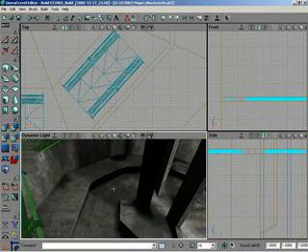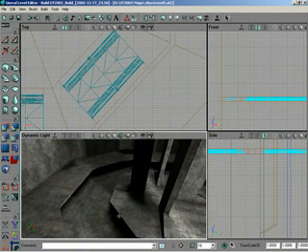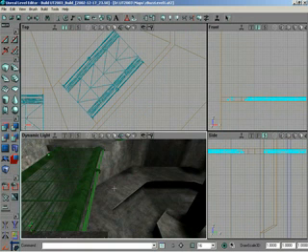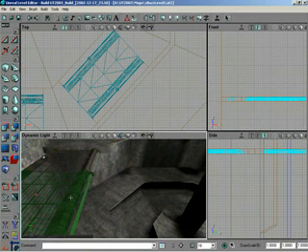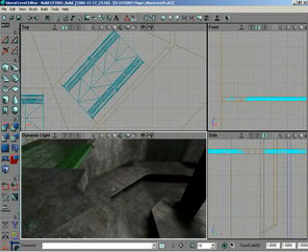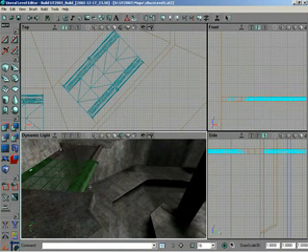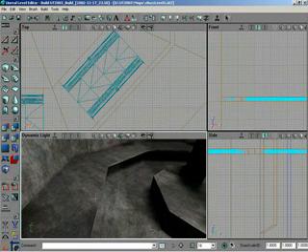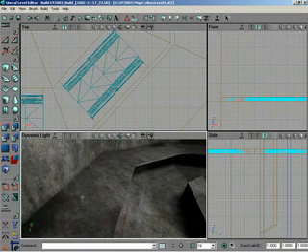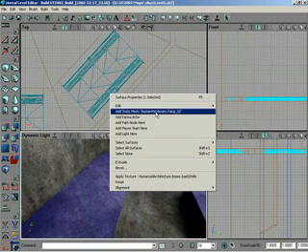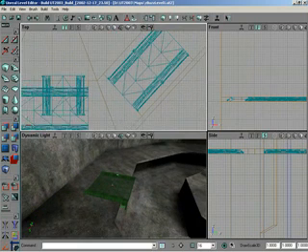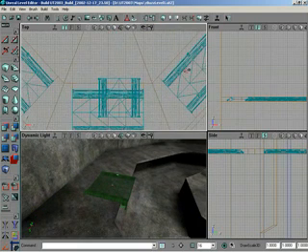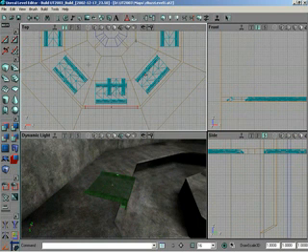Next, we want to go to the bottom and add little walkways across out to the start of the pillars. Now, I could just duplicate one more since we're going to use this static mesh for the walkways across here, but I kind of want to keep the groups clean and don't want to keep it inside this group. I'm just going to add a new static mesh of that walkway here. So I'll simply right-click, since I still have that one selected from the static mesh browser, and add a new one here. That way, if I went to the groups browser, this would not be part of the other group if I ever needed to adjust or make another duplication or whatever.